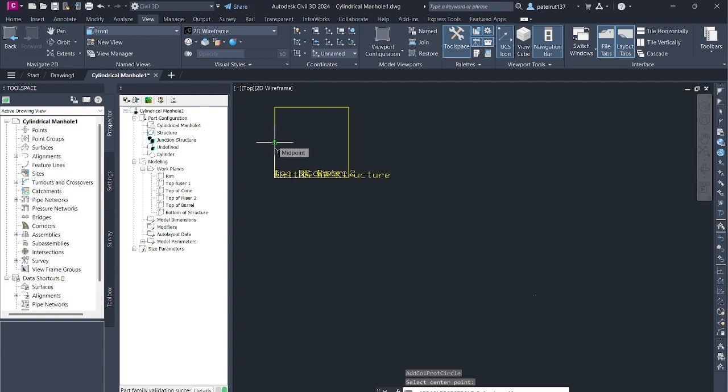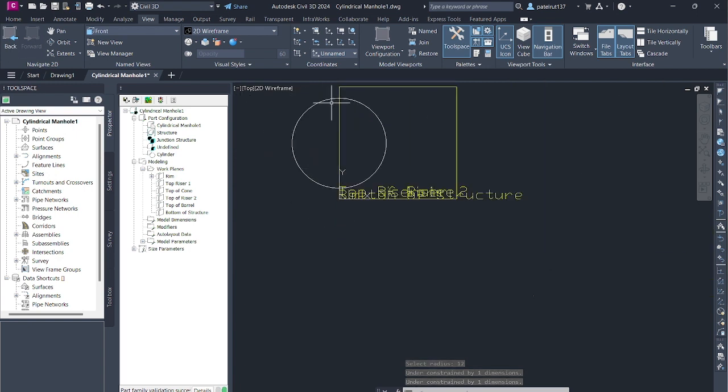Exit the Part Builder utility by clicking the small X in the upper right corner of the part browser. The part browser is the left pane portion of the Part Builder application window. If you are prompted to save the part, click Yes. Part Builder closes. Open the tutorial drawing called Part Builder 1a.dwg.